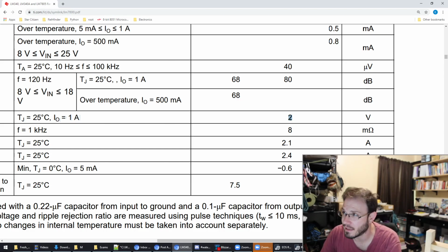I guarantee it. In 346 and 347, you almost guaranteed for certain you're going to construct something and you're going to want a fixed voltage. And so I want to give general guidelines that if we follow those good practices, we're going to have things that work. So always have that input filter cap, always have that output filter cap, and always abide by that 2.5 volt voltage drop, or I should say dropout voltage, and your regulator is going to work fine, I promise you.